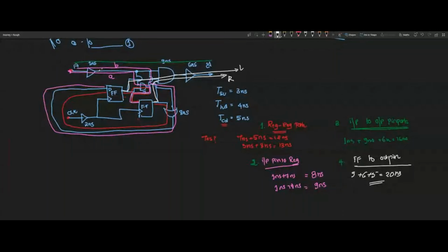Whenever you analyze at this point, if you see this particular NAND gate, in the interview they ask how much time it takes if I give any input, like A and clock, to stabilize the data at Y. If at time 0, 0 nanosecond, that is a reference point, I give some input, how much time does it take to stabilize the data? Such questions they will also ask.